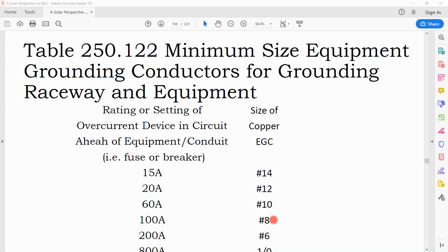The reason being, it's a little murky on whether you need a DC grounding electrode conductor, or if the components, all the metal frames and racking and boxing, simply need to be attached to your equipment ground.